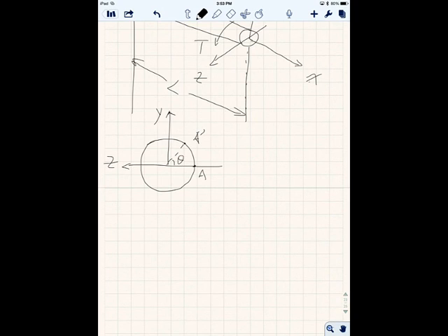This angle over here, we call it theta. Now, theta is quantitatively defined by the amount of torque you apply, the length of the beam, and modulus of rigidity, and also polar second moment of inertia.